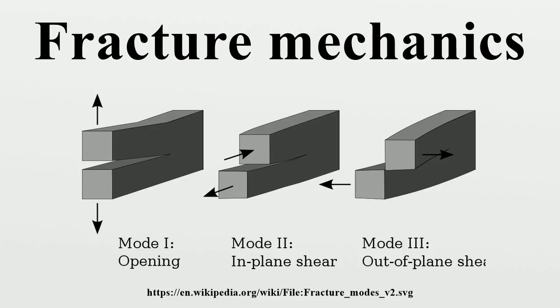In physical terms, additional energy is needed for crack growth in ductile materials when compared to brittle materials. Irwin's strategy was to partition the energy into two parts: the stored elastic strain energy, which is released as a crack grows. This is the thermodynamic driving force for fracture. The dissipated energy, which includes plastic dissipation and the surface energy. The dissipated energy provides the thermodynamic resistance to fracture.